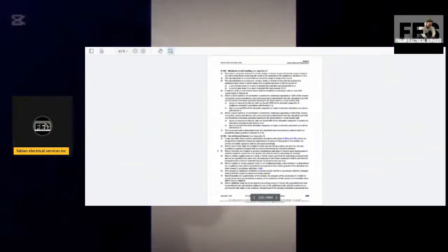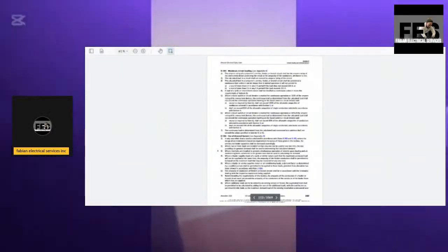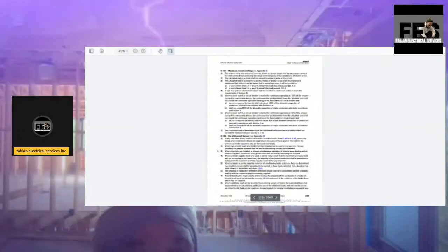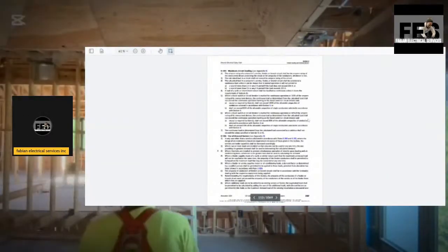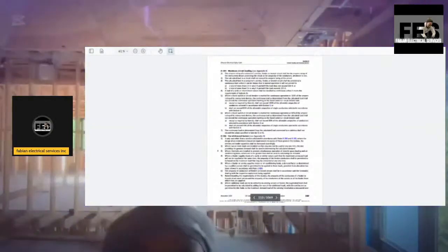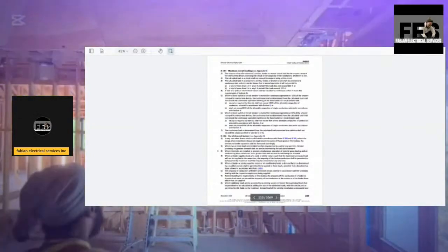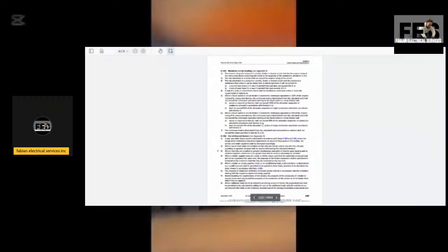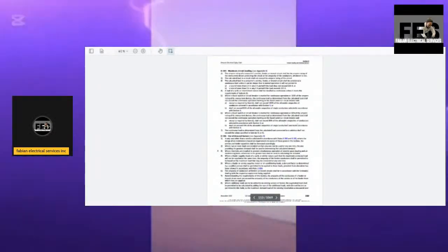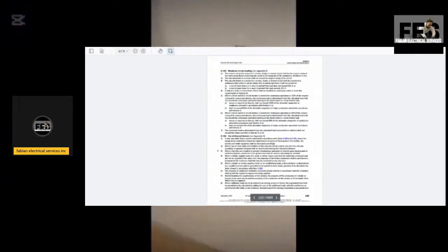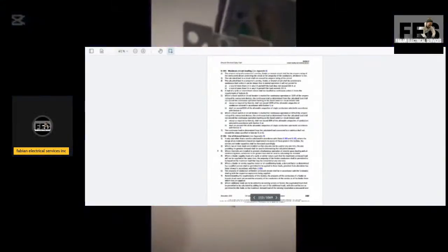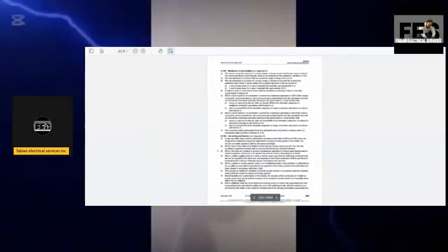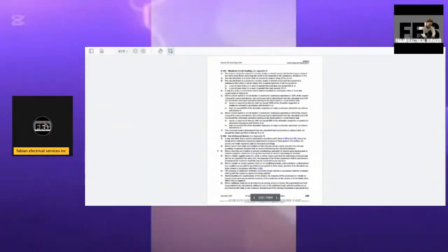Where a fuse switch or circuit breaker is marked for continuous operation at 80% of the ampere rating of its overcurrent device, the continuous load as determined from the calculated load shall not exceed the continuous operation marking on the fuse switch or circuit breaker, and except as required by item B, shall not exceed 80% of the allowable ampacity of conductors selected in accordance with section 4, or shall not exceed 70% of the allowable ampacity of single conductors selected in accordance with section 4.